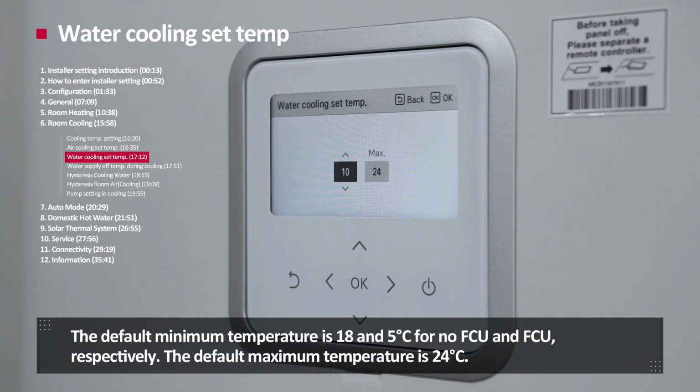The default minimum temperature is 18 and 5 degrees Celsius for no fan coil unit and fan coil unit respectively. The default maximum temperature is 24 degrees Celsius.